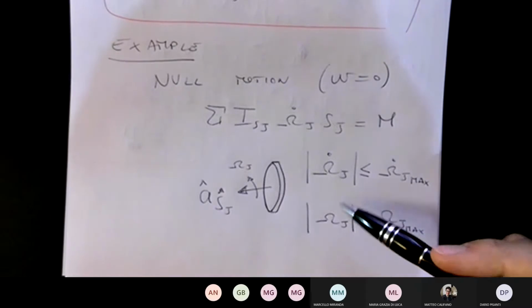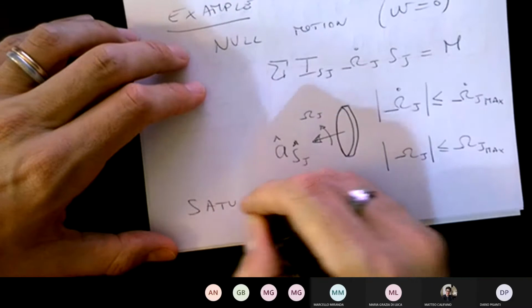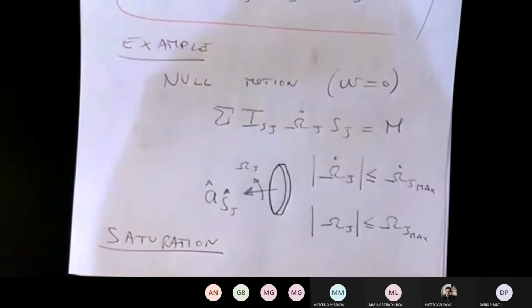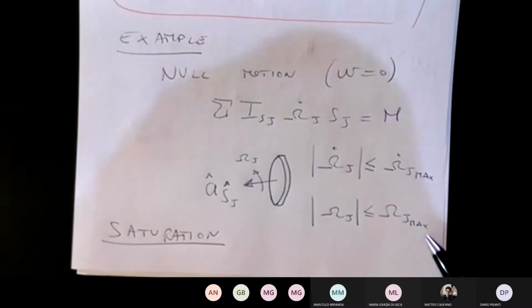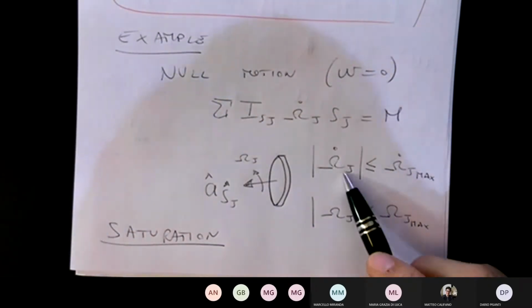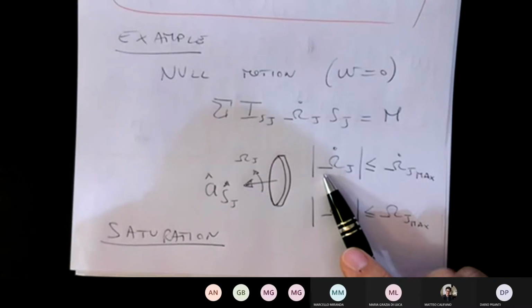So one problem with reaction wheels often is what we call saturation. In other words, for some reason during your maneuvers you have accelerated one wheel one way or the other and it's reached the maximum and you can't use it anymore. Or if you want to use it, you have to slow it down, bring it back to a nominal RPM value. But if you slow it down, that means you apply some omega j dot. So you are upsetting the orientation of your spacecraft to desaturate the wheel.